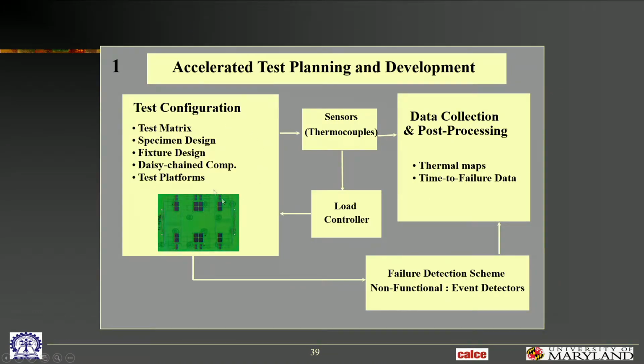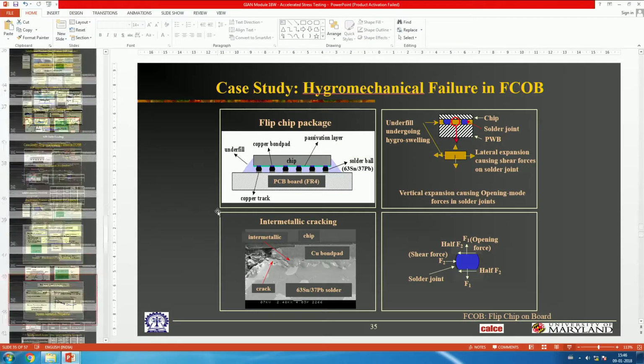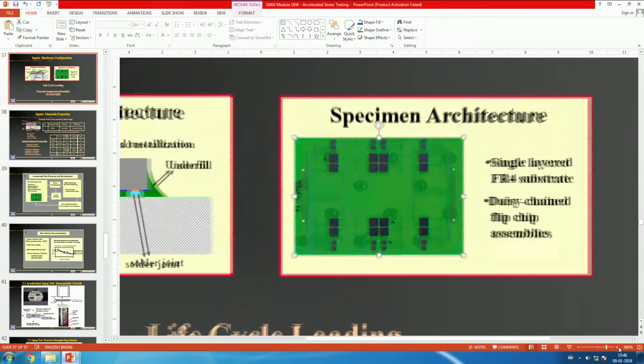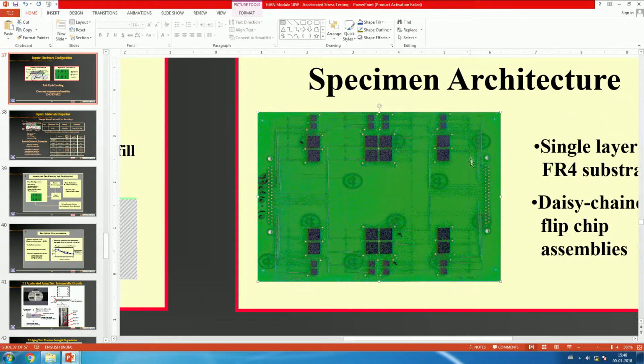So then we designed test specimens. So we came up, in conjunction with the sponsor, with test boards. Let's zoom into that a little bit. It's worth discussing this one. So the test boards look like this. These are simple printed circuit boards with bare die, flip chipped and soldered down to bond pads. Two different die sizes, 5 by 5 millimeter and 10 by 10 millimeter. There are flip chip bumps under them. You cannot see them from this side. This is the back side of the die. And there are various underfills inside.